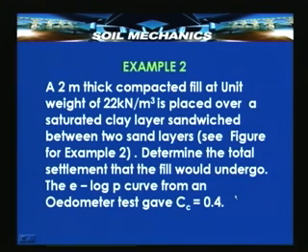Now, what is required here is what is the kind of settlement that will emerge due to this fill material itself. Now, this fill material has its own weight, and therefore, for all practical purposes it acts like a building and it imposes stresses on the clay layer and it causes the settlement, and that settlement itself is important from point of view of knowing what is the consolidation behavior of the clay.